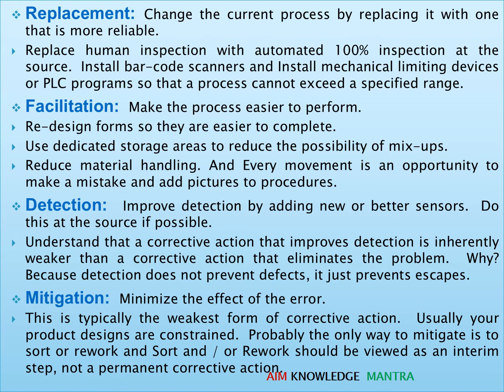Detection, improve detection by adding new or better sensors. Do this at the source if possible. Understand that a corrective action that improves detection is inherently weaker than a corrective action that eliminates the problem. Why? Because detection does not prevent defects, it just prevents escapes.